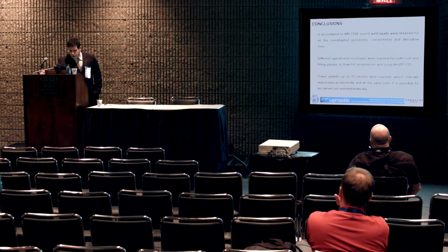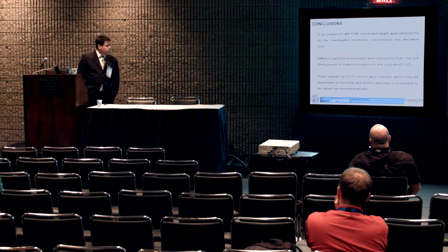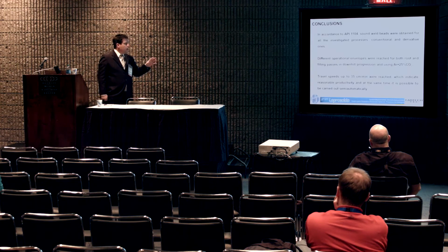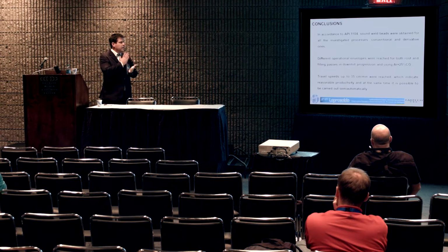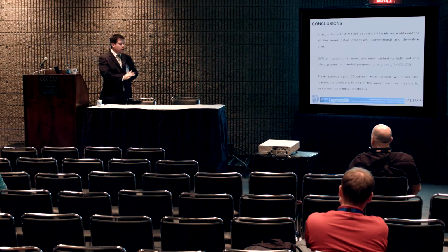Okay, so I'd like to draw some conclusions. In accordance to API 1104, we got sound welds obtained for all investigated processes. That is not completely true. I should have changed that because it was for root pass. Yes, for root pass, we got sound welds for conventional, CMT, STT, RMD.